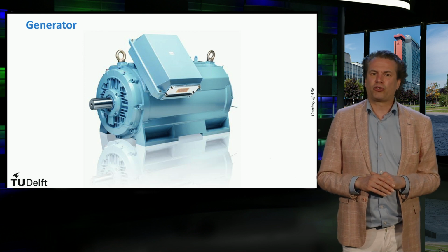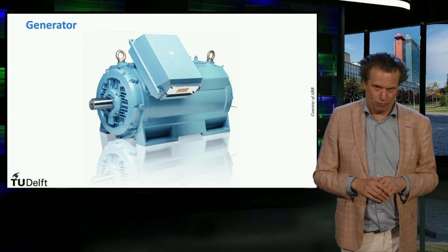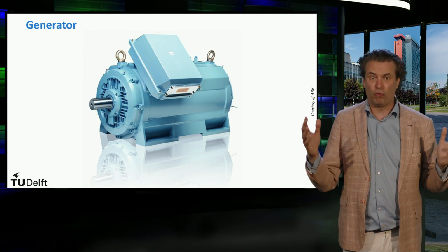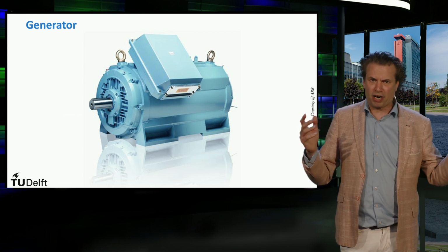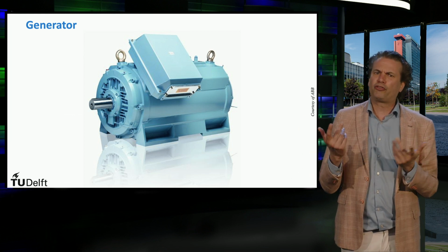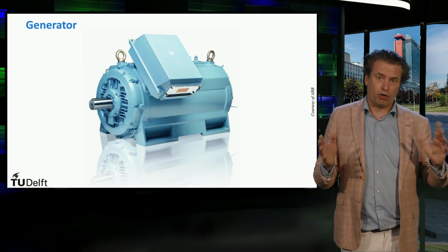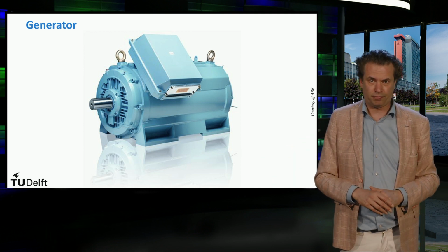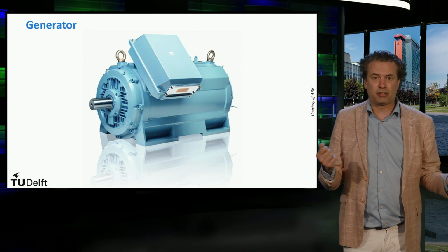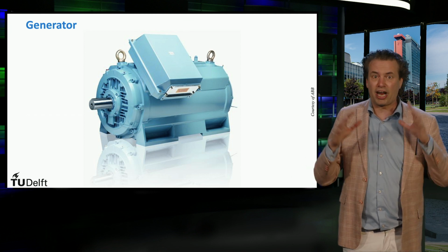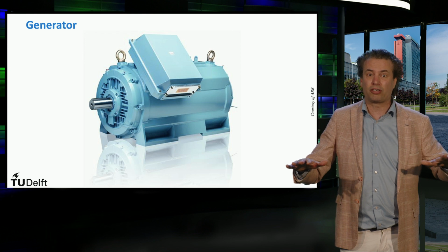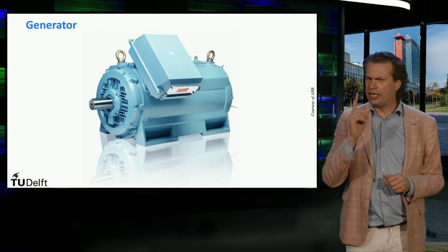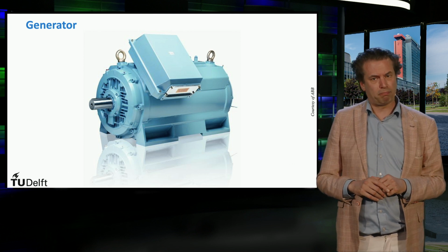Traditional power systems consist of an AC-based network. The grid works at constant frequencies: 50 Hz in a large part of the world and 60 Hz in the Americas and parts of Asia. In order to avoid problems with the functioning of the load, frequencies must be uniform throughout an interconnected grid. Control loop mechanisms built into the power generation sources are able to maintain a balance between connected load and generation within a small deviation in frequency. Here we will shortly discuss some control loop mechanisms.